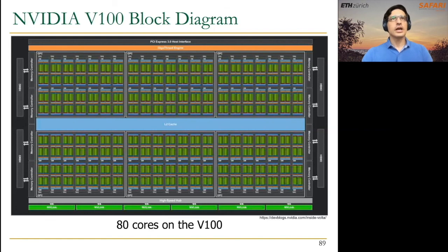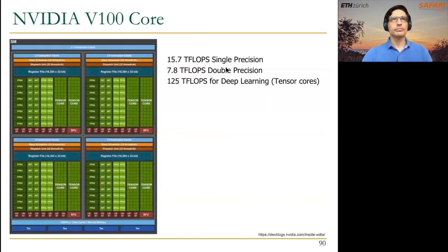Now let's take a quick look at the V100 SM, or GPU core. As you can see, it's divided into 4 main parts. Each is like a small GPU core inside a larger GPU core, right? Each of these parts contains its own warp scheduler to select the instruction from the warp that is going to be issued onto the pipeline next.